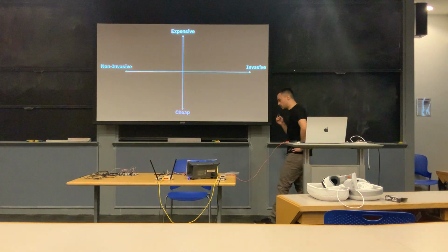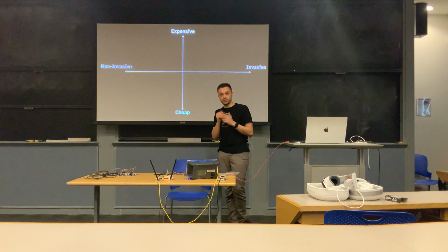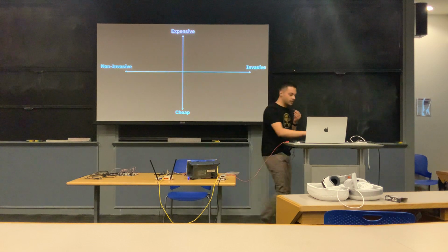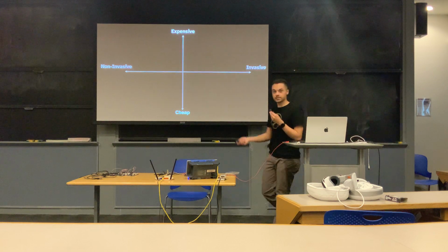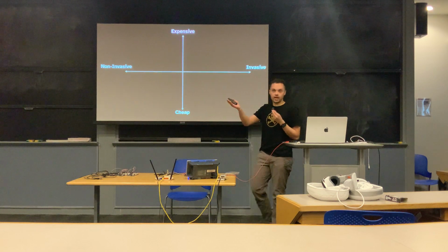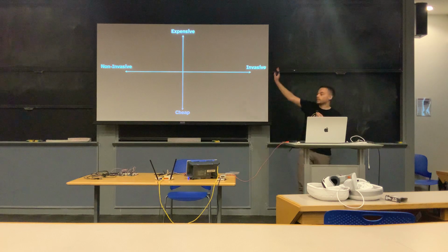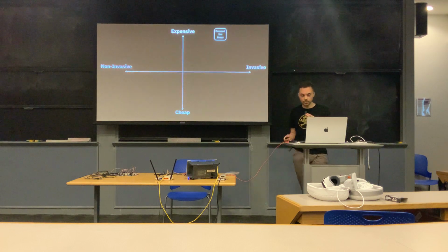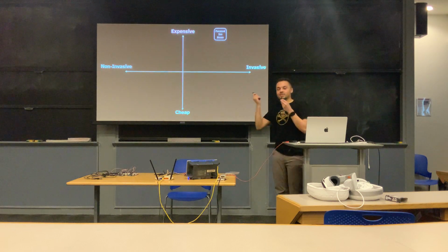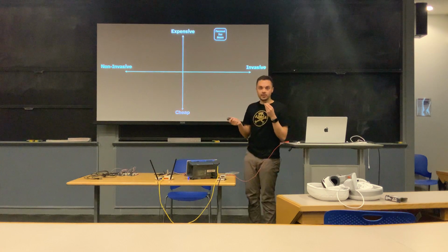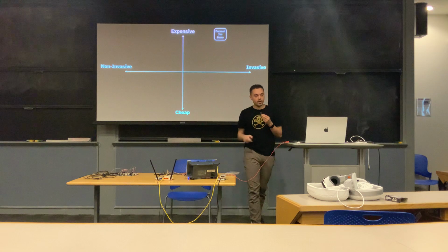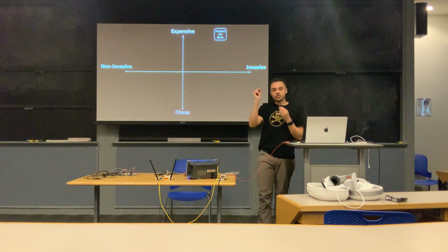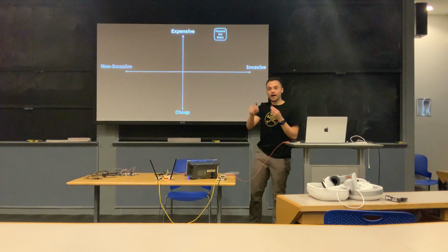And so I wanted to kind of plot out some of the different attacks that people can do against these chips. So on the x-axis here, we have the level of invasiveness. On the y-axis, we have the expense. And so we'll just list off a couple common hardware attacks and just plot them against this plot here. So my personal favorite, I think the coolest thing you can do is this thing called a focused ion beam. And so this is actually used a lot in like material science research and metallurgy, where you're able to actually inject directly into the silicon, modify the silicon itself.